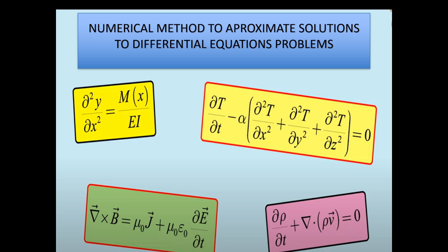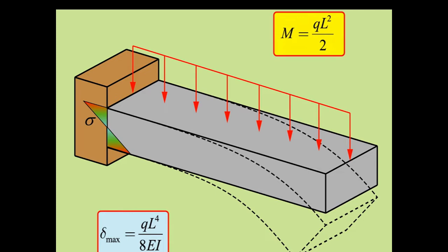Most engineering analysis requires solving complex differential equations, such as heat transfer, fluid mechanics, electromagnetics, or structural analysis problems. The finite element method approximates solutions to these complex calculations so they can be solved with a computer. Let's see what the method consists of by applying it to a structural analysis case, when we want to analyze the stress in a beam due to applied load with respect to the deformation of the material. We can do it thanks to the equations of material strength.